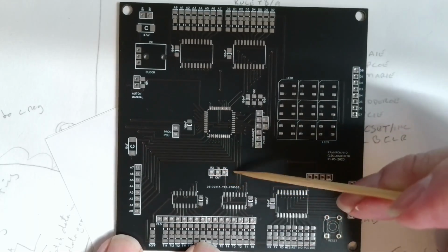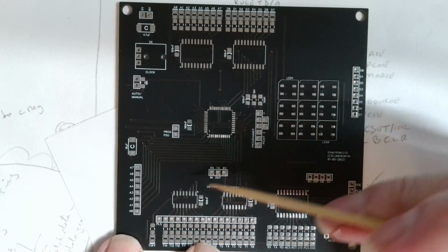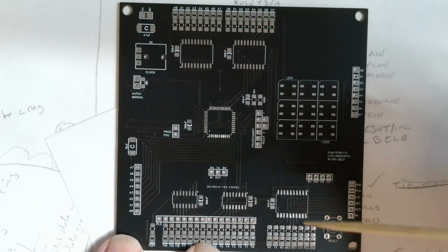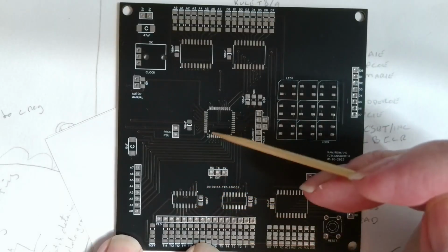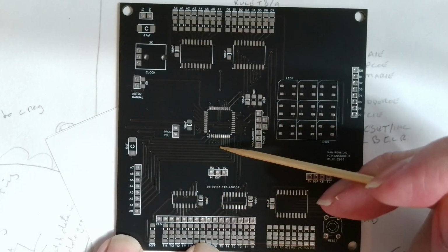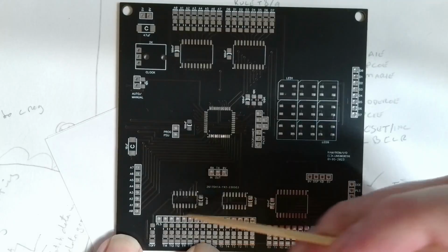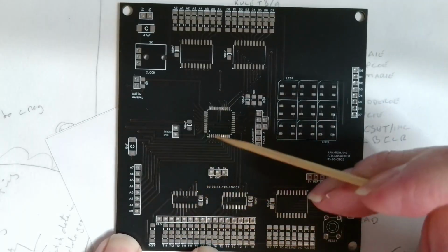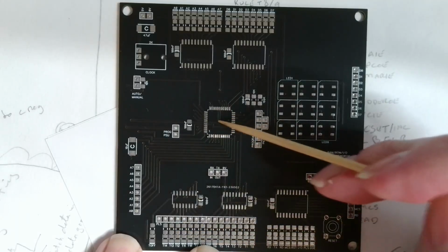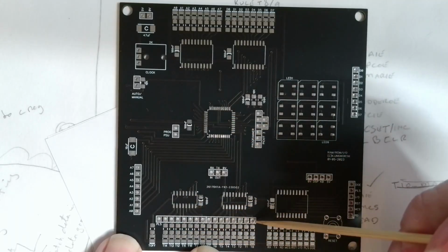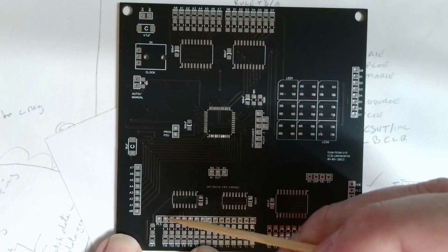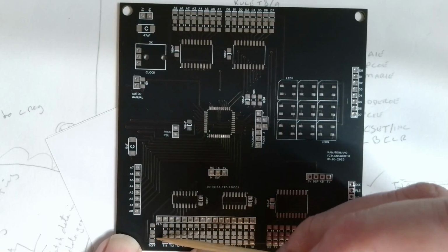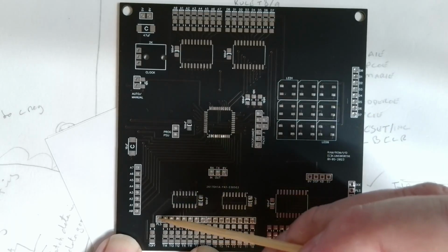That's your comms port that wasn't actually used for anything. Here are the two 74238s for demultiplexing 4 address lines that come off the PIC chip, and that's 16 possible outputs, which is your T states. So I'll just give 4 bits out of there, because I was running out of I/O on there, so I demultiplexed it. And we use 0 to 14. 15 goes off on its own. You've got an LED there for it, but I feed the reset signal through here.